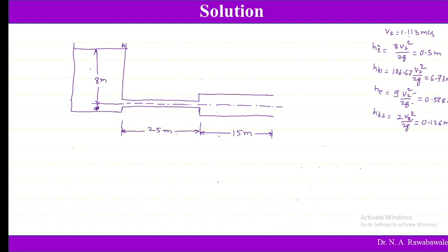So first we have marked point A at a distance of 8 meters from the center. First of all we reduce this distance by 0.5 meters. 0.5 meters means on this graph we have to take 0.5 centimeter, which is 5 mm. So we have to mark point B here. Point B is marked, and this is HI, which is reduced from point A.